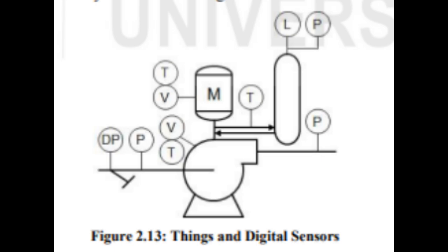Source: IIoT architecture, standards at every level lets you change wherever by Jonas Burge, www.linkedin.com/pulse/iiot-architecture-standards-every-level-lets-u-change-jonas-burge. With hundreds or thousands of pieces of equipment in the plant to be monitored, this can translate into many hundreds or thousands of sensors, often referred to as pervasive sensing. Hardwiring each sensor signal point to point would require an inordinate amount of wiring and I/O cards. Therefore, these applications lend themselves very well to digital networking, bus or wireless.